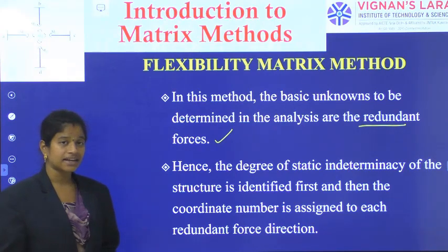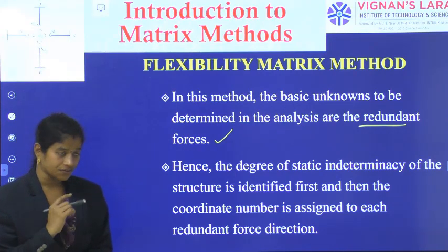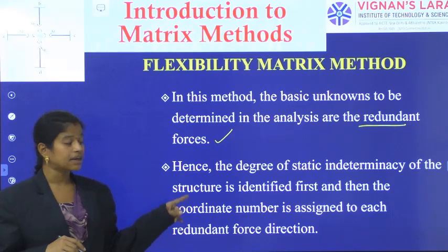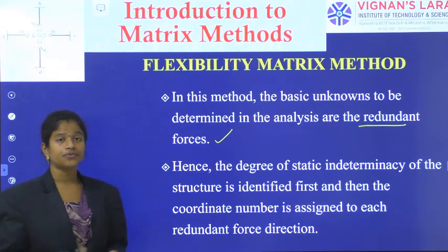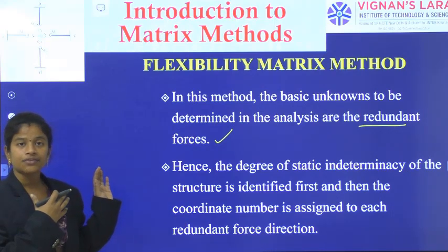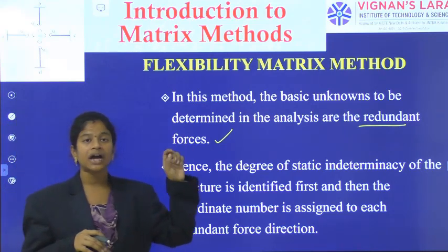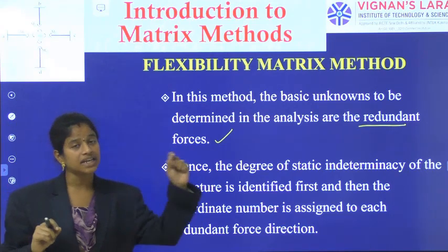Hence, the degree of static indeterminacy of the structure is identified first. Then, the coordinate number is assigned to each redundant force in the direction. How we have done in our frame. Okay, so we should have to identify what is the redundant force, what is the unknown force.